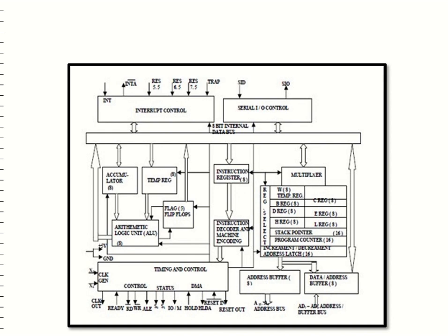General purpose registers. There are 6 general purpose registers in the 8085 processor, that is B, C, D, E, H and L. Each register can hold 8-bit data. These registers can work in pairs to hold 16-bit data, and their pairing combination is B, C combined, D, E combined, H, L combined.